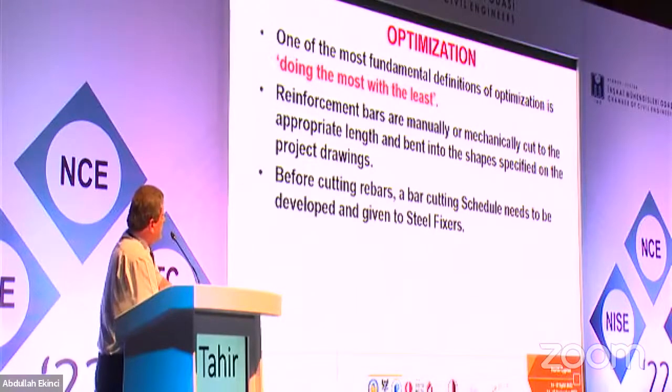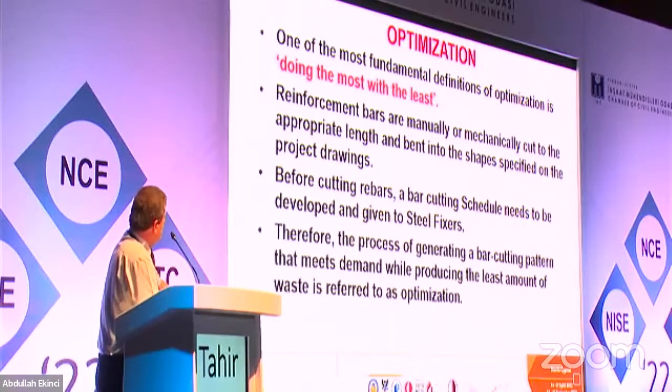Before cutting, a bar cutting schedule needs to be developed and given to steel fixers. Many years ago, while I was doing my study and case studies in Britain, I learned that in Britain, a steel fixer cannot start to cut reinforcement by himself. He prepares a schedule, he goes and gets the approval of the engineer, and then he applies it, which is not the case in our country here.